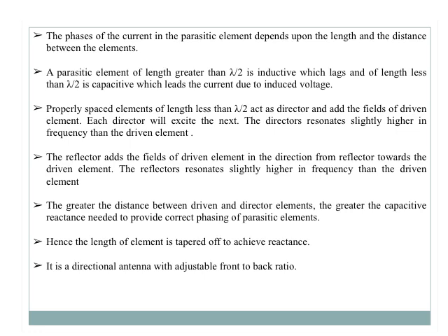The phases of the currents in the parasitic element depend upon the length and distance between the elements. A parasitic element of length greater than lambda by 2 is inductive, which lags, and of length less than lambda by 2 is capacitive, which leads the current due to the induced voltage.